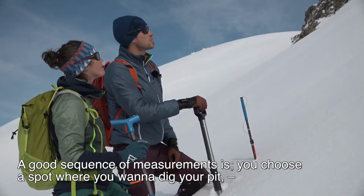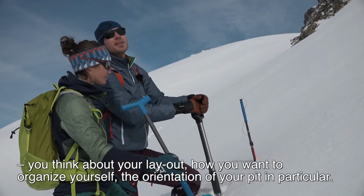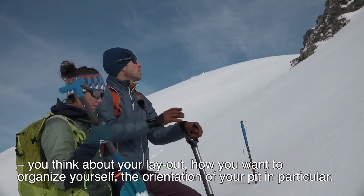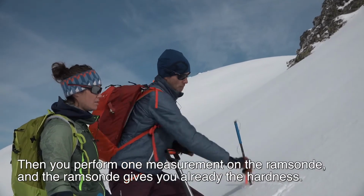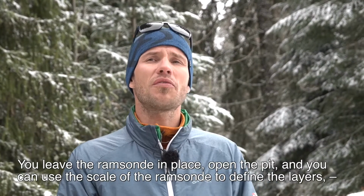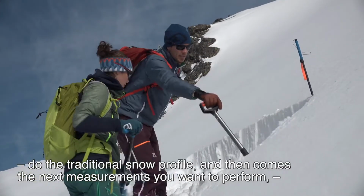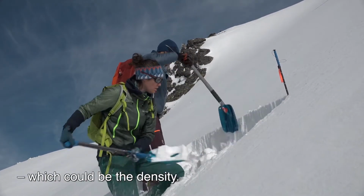Typically a good sequence of measurements is you choose a spot where you want to dig your pit, you think about the layout, how you want to organize yourself, what the orientation of your pit is gonna be, of the pit walls in particular. Then you perform one measurement with the ramsonde, and the ramsonde gives you actually already the hardness. And then you leave the ramsonde in place, you open the pit, and you can use the scale of the ramsonde to define your layers, do the traditional snow profile, and then comes the next measurements you want to perform, which could be the density.